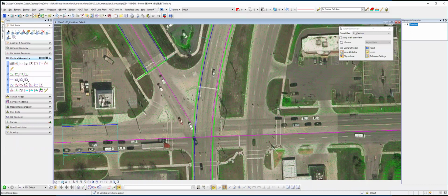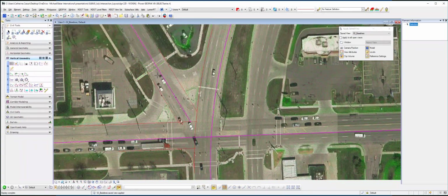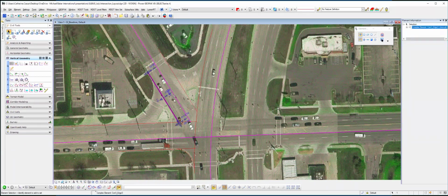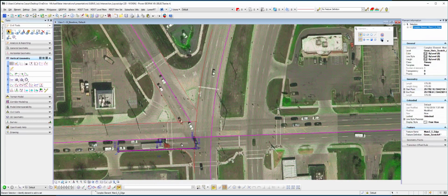So the place to start is to identify some baselines. These baselines here are all smart geometry. And you'll notice I'm doing these off of the alignment. This is to eliminate the possibility of circular referencing that comes into play a lot of times. This particular edge, this is the seam of my model. So this actually is built off of the corridor. Its parent is that corridor edge.